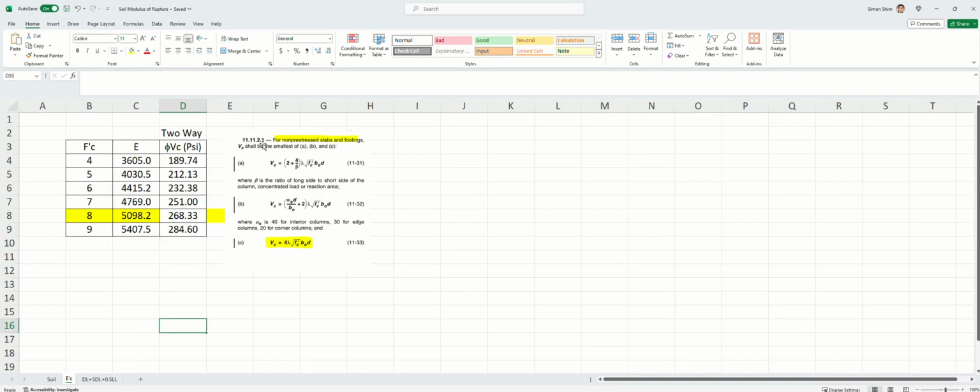So in concrete ACI 318, we have a one-way shear concrete shear capacity. Typically for a two-way kind of system, we have 4 times lambda times square root of f'c. That is the concrete shear capacity in stress. But if you multiply by the width and depth, obviously that makes the resultant forces, right?